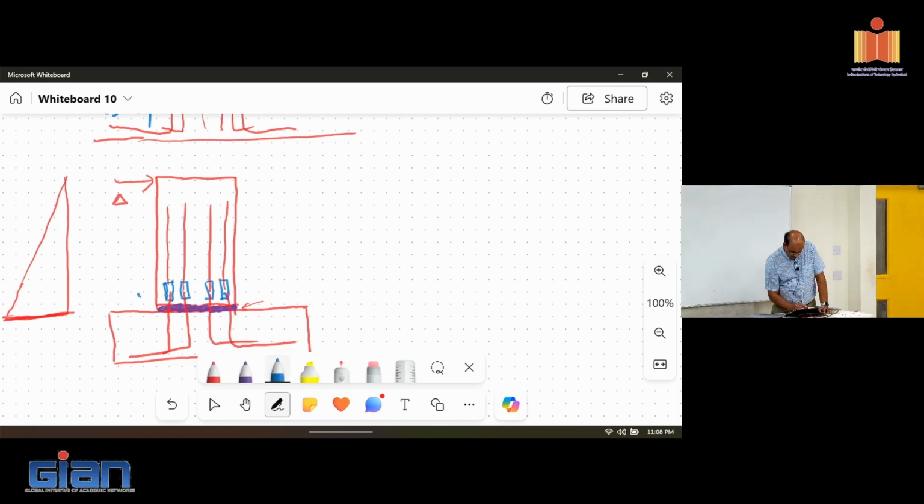So a crack could be developing right here, or it could be developing underneath the grout pad, depending on how cohesive the grout pad or the interface material is and how it's attached. Sometimes they roughen the foundation and then the grout pad will stick to the foundation, and the crack will develop above. It's very unlikely you're going to tear the grout pad apart. They would use some kind of a fiber reinforcement in there, typically non-metallic, to make sure the pad stays together.